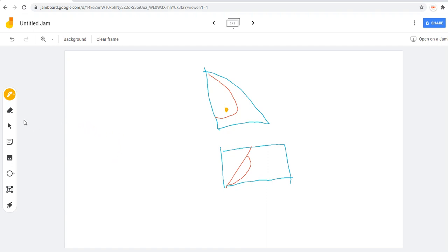And we're going to construct what we call the tie line that will pinpoint to us the location of the raffinate and the extract layer. By the way, class, when we speak of the extract layer, it's here on the upper part of the phase envelope that you can see the extract. The raffinate is written here below. So the process of determining the composition of the extract and the raffinate layer here is really graphical, and it's trial and error.